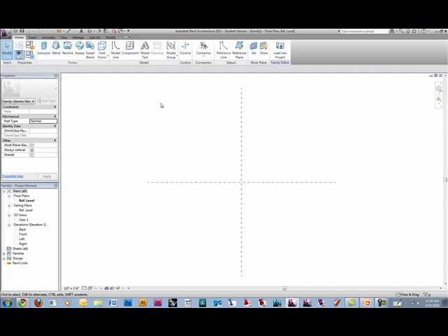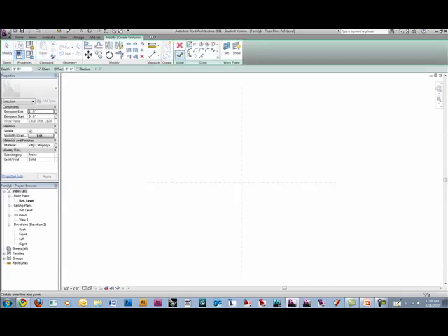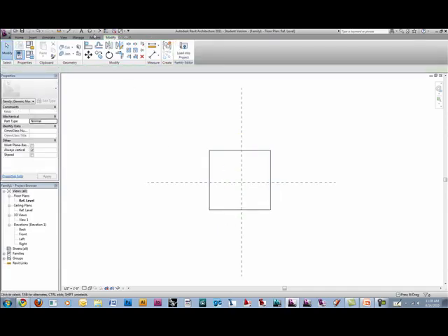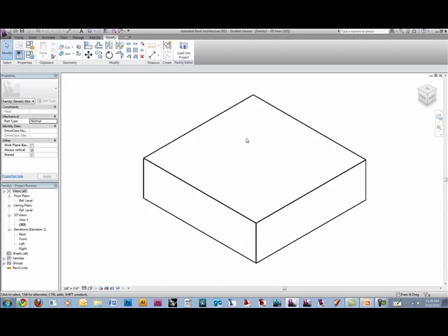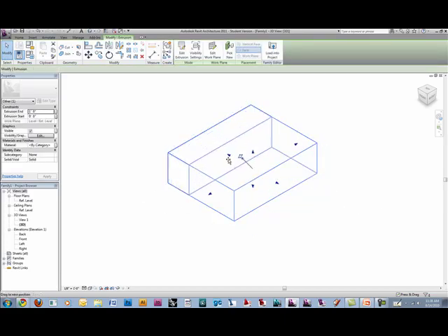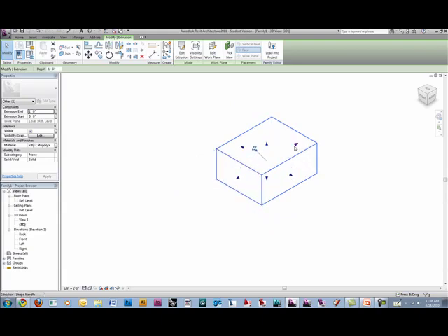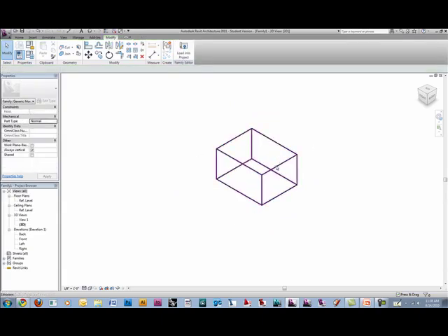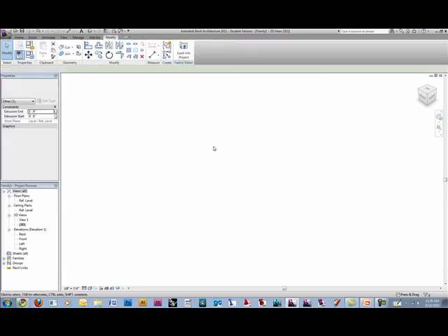Most people want to go straight up to the extrusion tool, and let's say we're going to make a cube, they're just going to make the cube. And then they're going to say finish, and there's their cube. And that's what they want to call it. Done. Make it whatever size you need it, and all of a sudden you have your cube. That's what most people do. But we're not most people, so we're not going to do it that way. That's not parametric at all, so let's delete it.